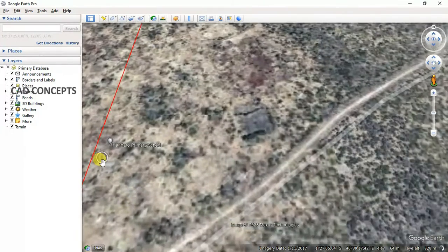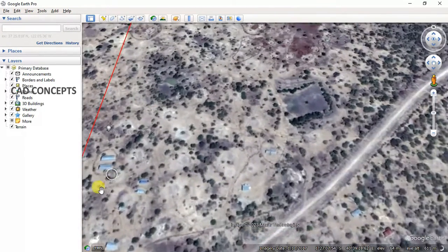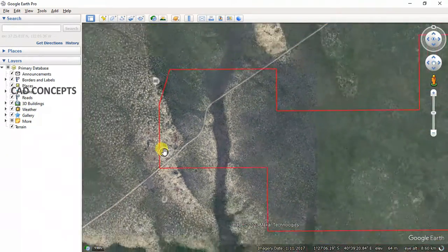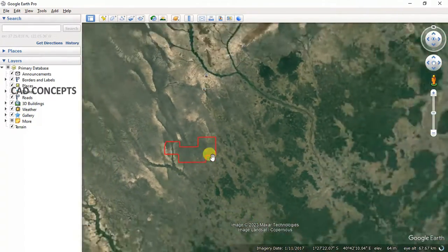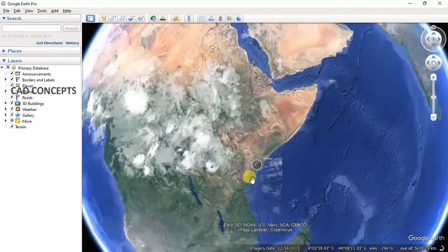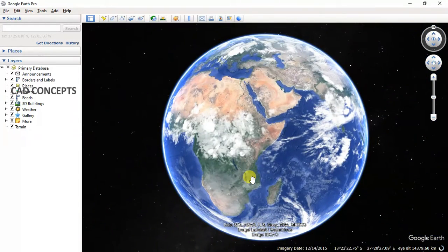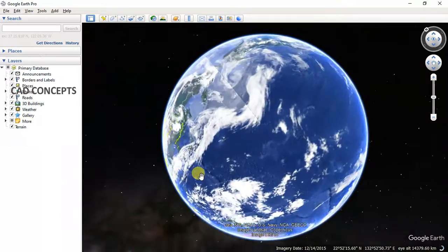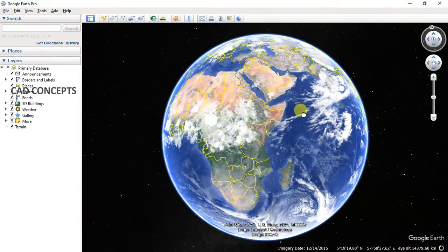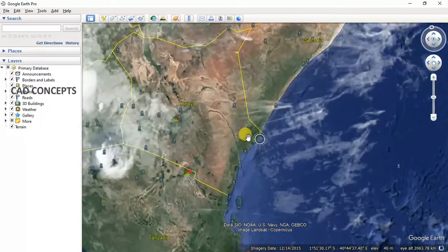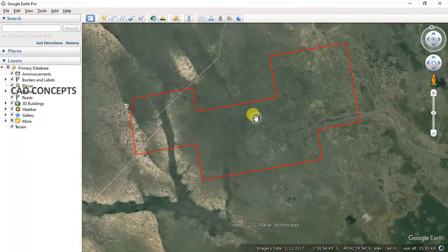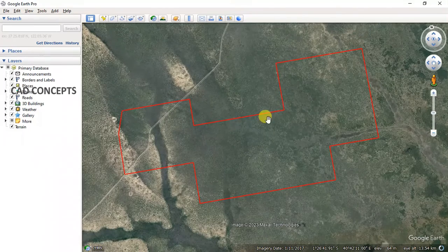You must have to provide exact coordinate and you can access directly Google Earth by drawing to KML feature very smoothly. As you see here, we are getting our location just from AutoCAD directly to Google Earth. Something like this we are getting here. So as much as exact your coordinate, you will reach exact to the point.